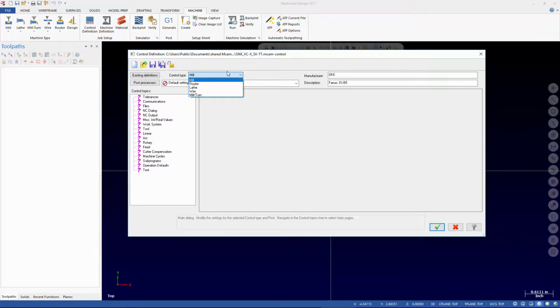In practice, almost nobody does this. And the reason is that unless you really know how things work in the background, it's a good way to get the wrong set of settings at the wrong time. The common complaint is that people go and upgrade Mastercam and their settings for their post change. And the reason is because they didn't set the control definition defaults from the very beginning.